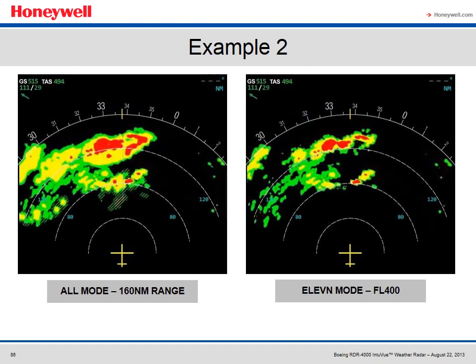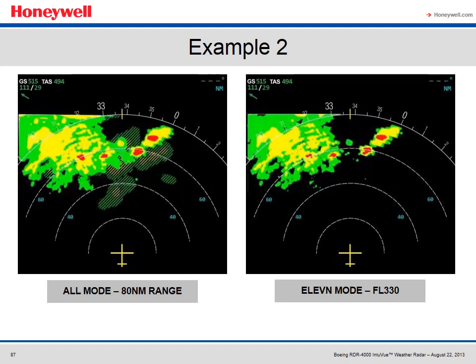But so far, the analysis shows a weak part of the line directly ahead of the aircraft. The line is now just outside 80 miles, and the 757 has climbed to flight level 420. Again, the auto mode alone might be interpreted to indicate there is no path through. Looking at an altitude slice at flight level 400, the analysis shows that most of the action is to the right of track, and the potential path through is persisting. The cells in the example are now at 60 nautical miles.